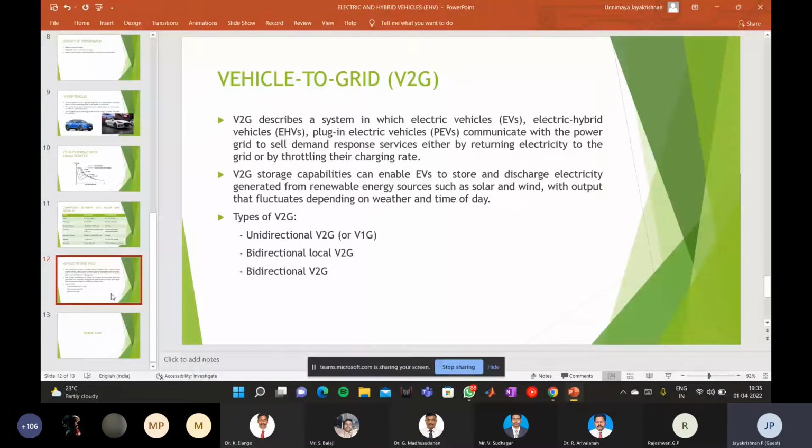And when we were leaving the resort, the charge was only 39%. And as I stated earlier, after traveling these 10 kilometers from the resort to Madikeri, it came to almost 30%. So while climbing down the hill from Madikeri to Sampaje, 10% charge was regenerated in the vehicle, and I had a 40% charge when I reached Sampaje down the hill.